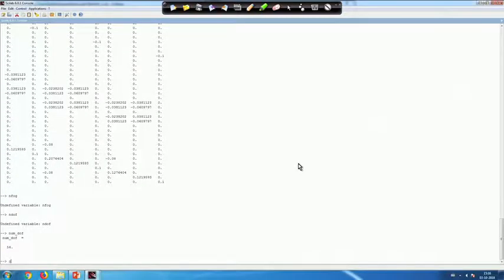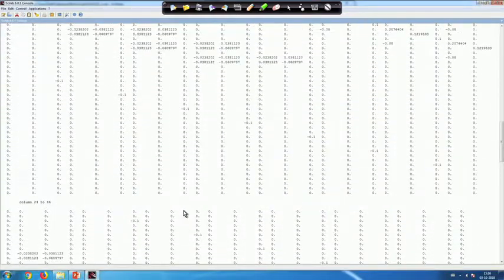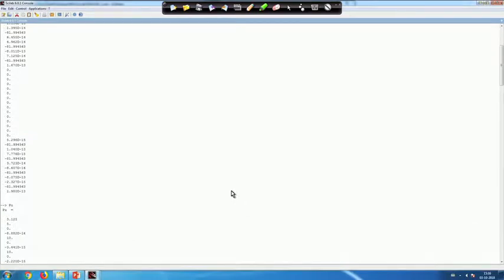It is just not numbering haphazardly. We check the determinant of kg, just a cross check. The determinant of kg is 0, it has to be because the boundary conditions were not satisfied. So now you can explore, as I said, these codes will be uploaded on the forum. This is a very basic code. Some of the information you have to give manually. But it gives you a flavor of computer implementation of the method. So you can further explore it.